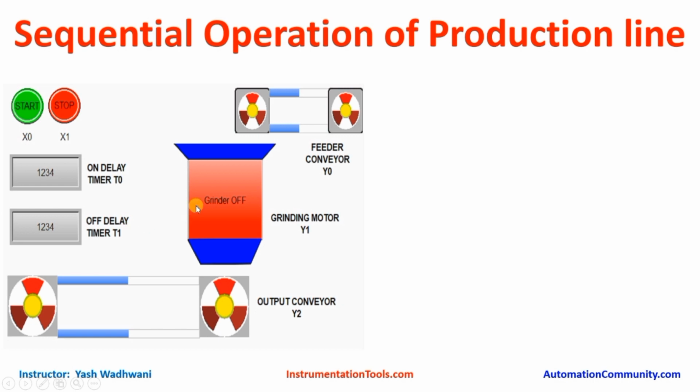Now assume if I turn on this machine before turning on the grinder, then what will happen? It will start transferring material to my grinder. Now if I turn on my grinder, it will not start and will trip because of overload.